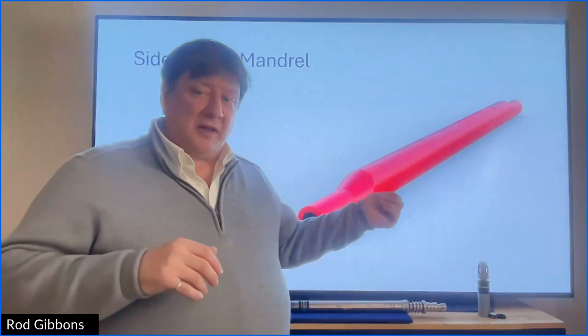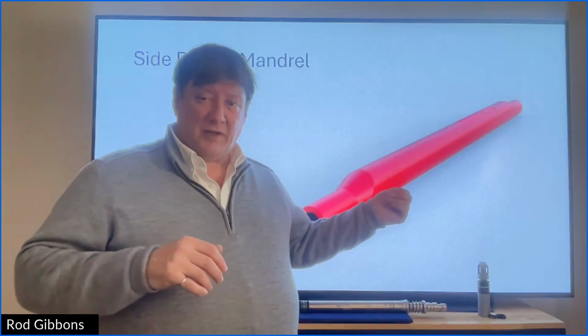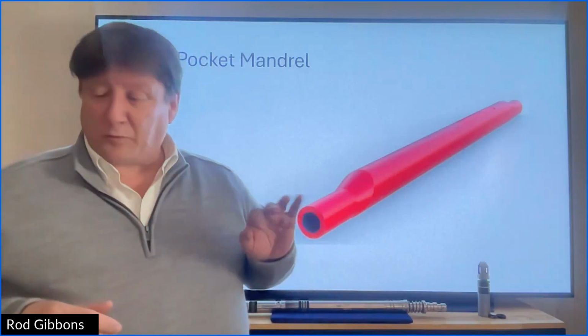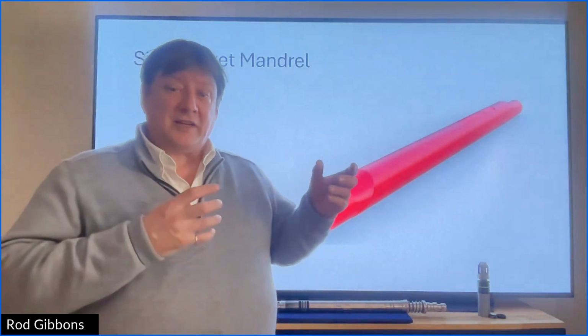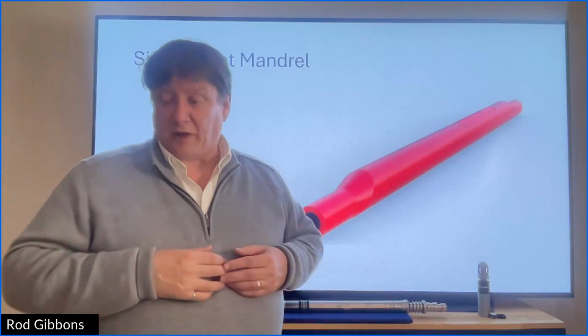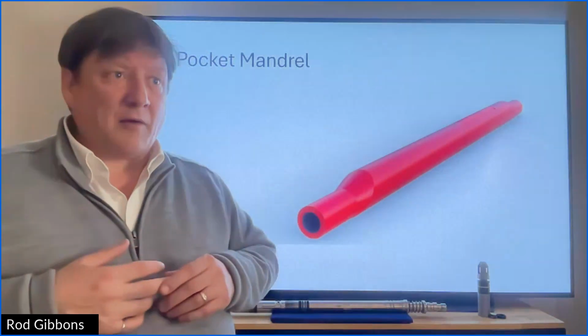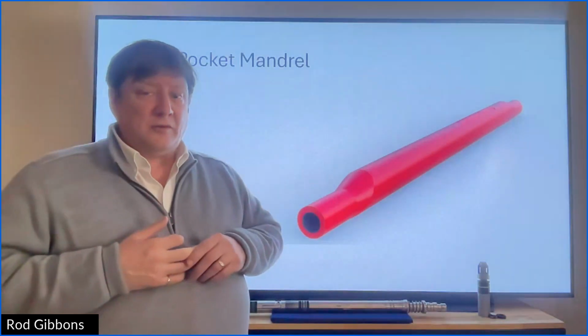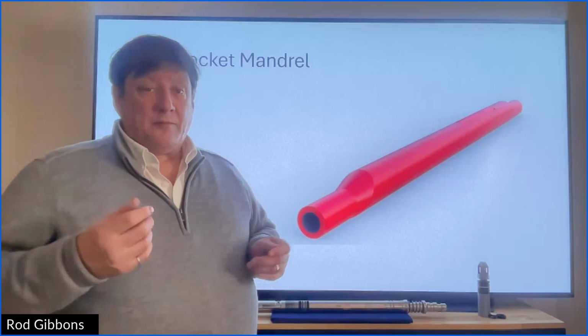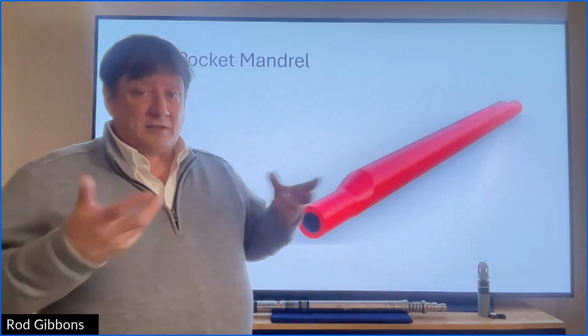Sometimes you will run the gas lift valve pre-installed when you run the side pocket mandrel in the tubing string, so it's actually sealing as it's being run in the well. I would say that's a very common way to run gas lift valves, mostly for the reason that it's already installed.